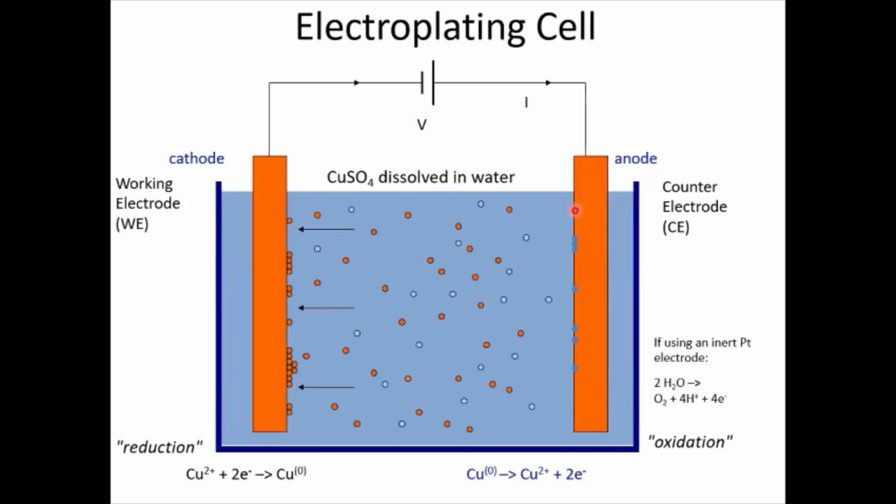There will be a reference electrode close to the anode, but as a two-dimensional figure, I have shown only these two. So once you apply, depending on the electrochemical reactions within the electrolyte and distance between the electrodes and other parameters, you have a deposition of these metallic structures on the cathode and evolution of oxygen or some gases at the anode. Suppose if there are some kind of oxides, there will be the deposition of oxides at the anode. Most of the metal reactions are reducing reactions, which will occur only at the cathode. So this is where you get deposits, called the working electrode.